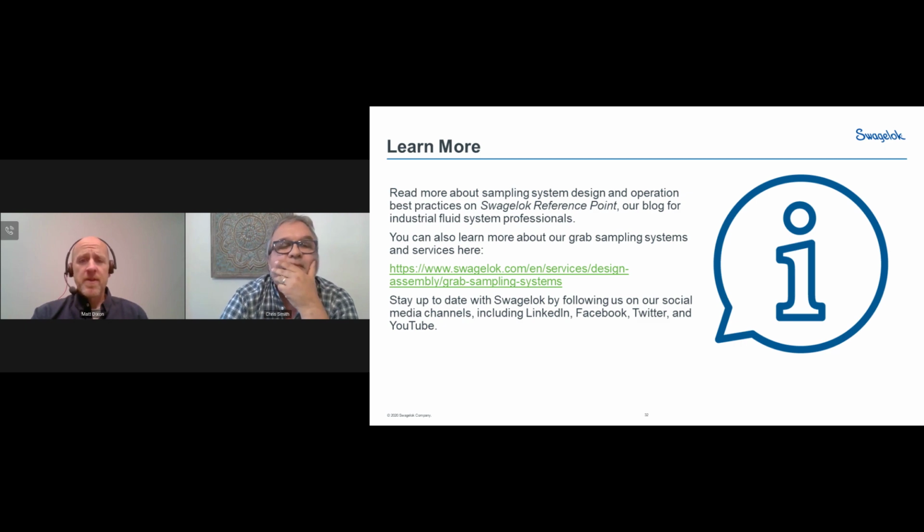I showed you that pneumatically actuated version that we were using to create a fixed volume sampler. Imagine if you were going to do that and periodically take a sample. Maybe you've got multiple sample containers lined up, and you could take multiple samples. Do that on a flow basis, so that you end up with a representative sample across a certain amount of time.